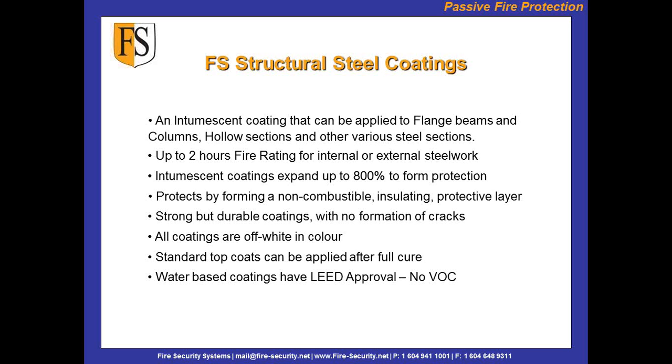and press down. What that does is that traditionally a lot of intumescent coatings for steel would crack on the flange edges. That's where they traditionally crack through movement, and that reinforcement stops that cracking. So you would put a light coat down, you would roll in the mesh reinforcement, and you'd put a top coat down over the top of that, usually about half the thickness. If your thickness was 2 millimeter dry film, you would put around 1 millimeter down, then reinforcement, then another millimeter, and then you would be complete, and that would stop that cracking. And a lot of our competitors' coatings still have that. Luckily, we don't have that at all. There's no need for it.